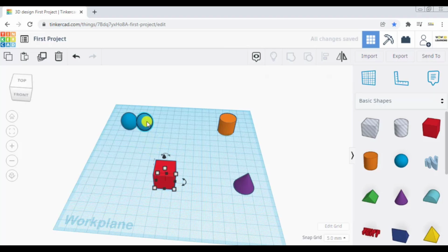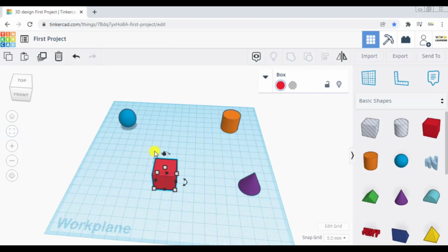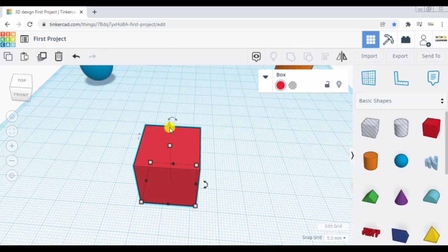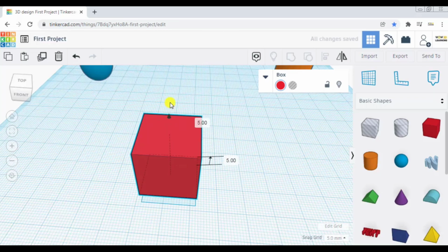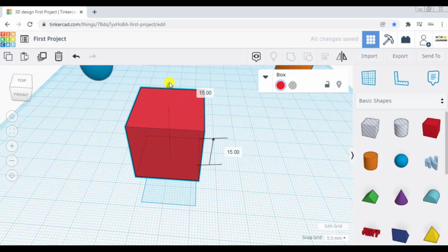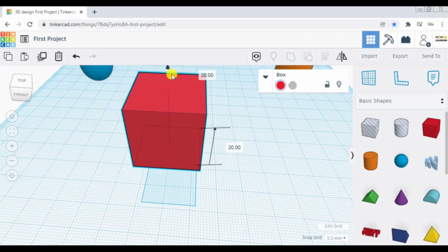This is a copy which has remained here from the previous selection. I will delete it. So now we will see motion in the Z direction, that is upwards. Now if I select this box and go to fit view, you see on every object when you click there is a triangle. This triangle is for moving the object in the upward direction. So when I press and click my left mouse button, you can see this distance from the bottom is coming.